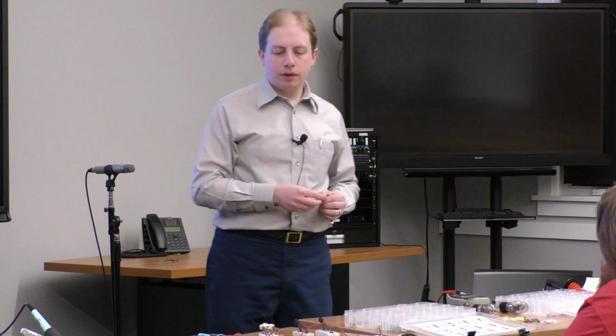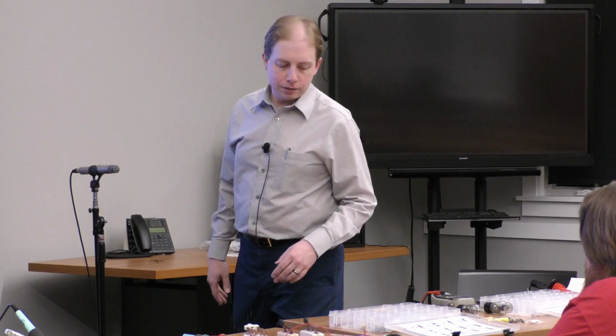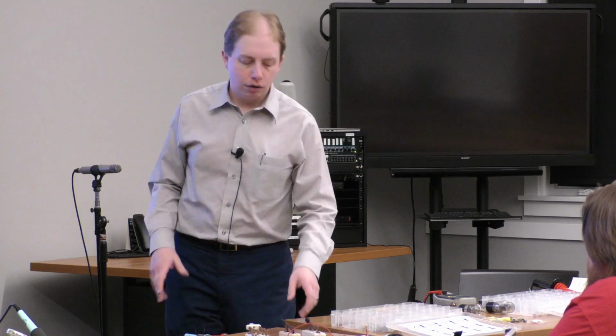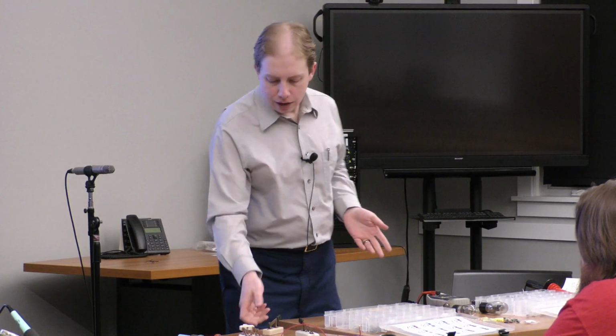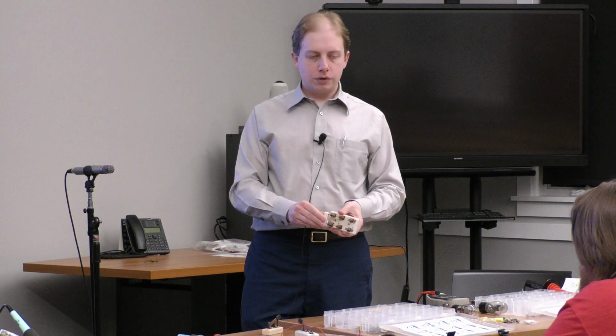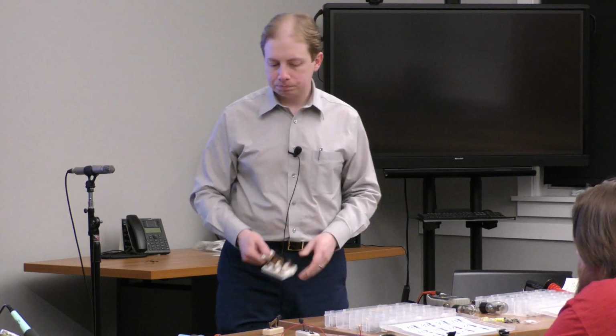Truly, there's a lot of overlap between transistors and relays, and some transistors can be used as relays. The big difference is relays are on or off, and usually they're controlling higher currents. With a relay, you've got a solenoid, a big coil of wire, and something that can move, and it's physically opening and closing that switch for you. Usually there's a set of contacts opening and closing inside the relay. But even relays can have multiple poles and multiple throws.